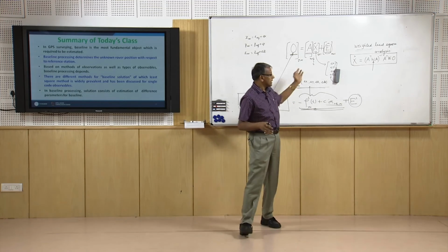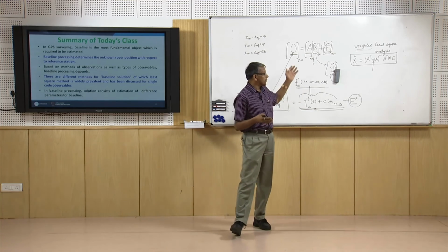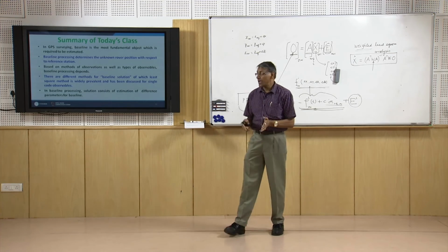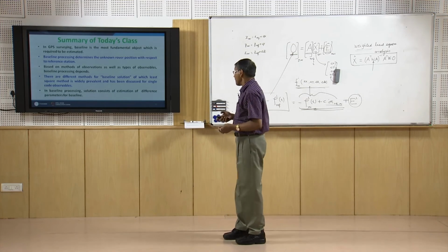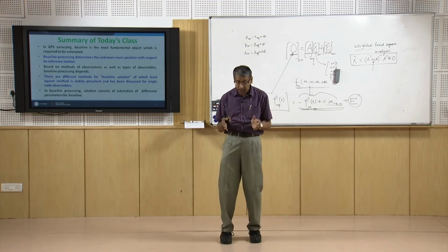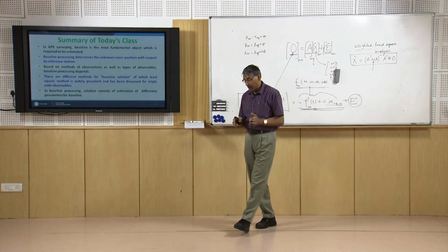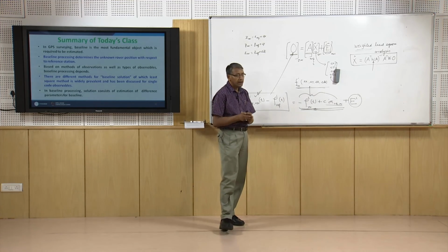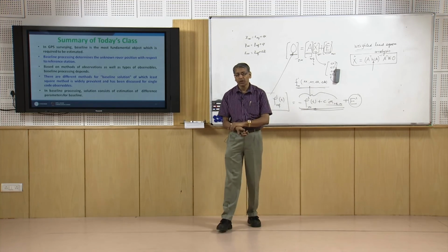In this class we discussed how to process the GPS data to end up with the solution for the baseline parameters using single code GPS observables, and at the end of this baseline processing we end up with parameters which define the different components of a baseline, which may further be added to the original reference coordinates to find out the location of the rover receiver.